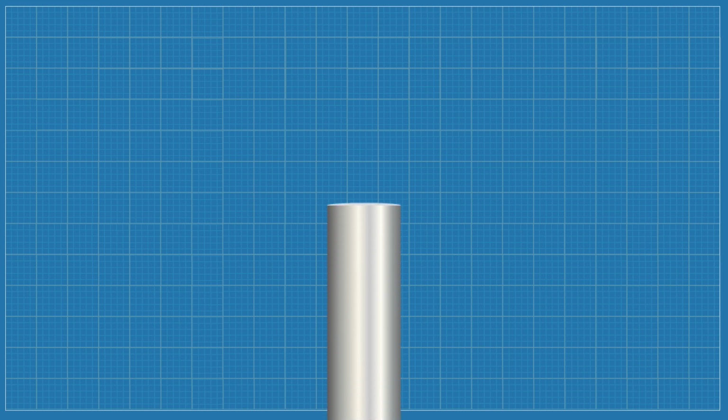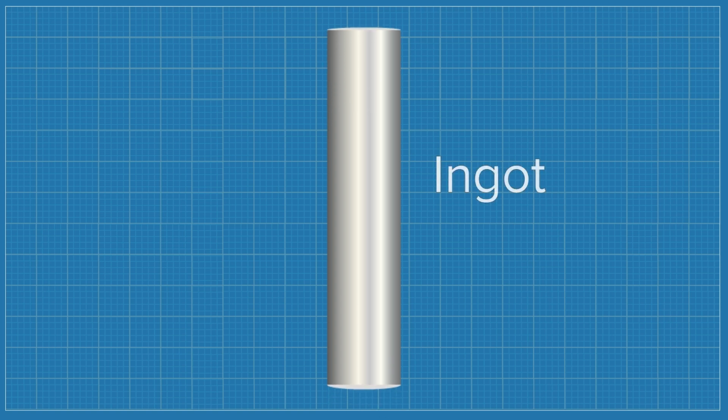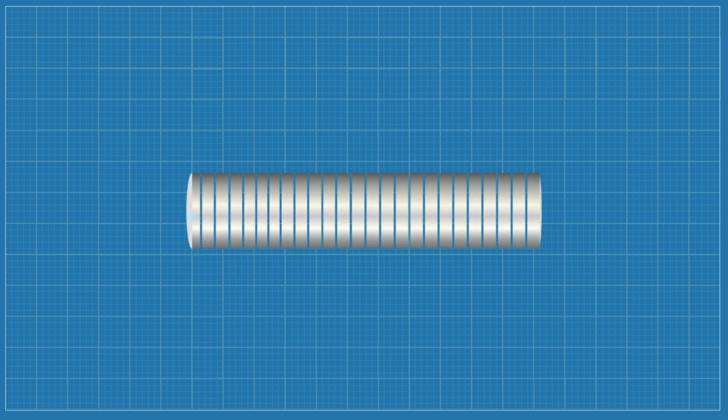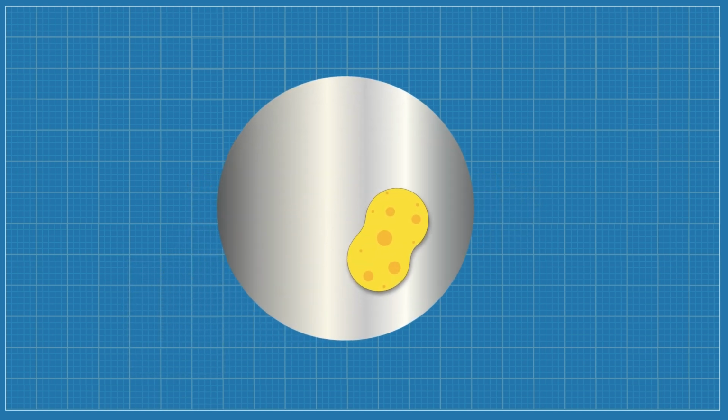Now that we know the different chip types, how exactly are they made? A basic overview of the manufacturing process begins with the initial construction of a silicon pillar known as an ingot. This is created when sand is melted into a liquid and then solidifies through crystallization. This ingot is then sliced into thin discs known as wafers. Once sliced, the wafers are polished for a smooth, clean surface.